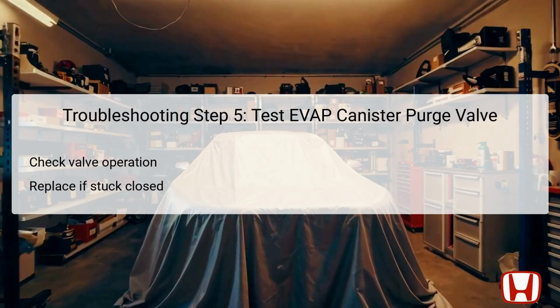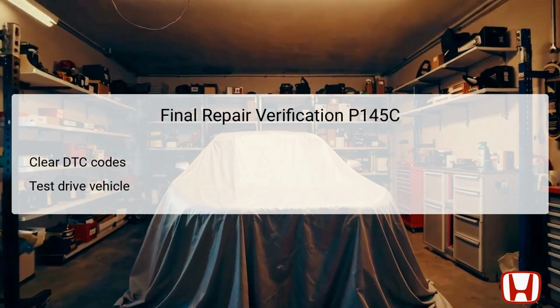emissions issues. After completing the necessary repairs prompted by the troubleshooting for DTC P145C, it is imperative to perform a final repair verification. Start by clearing any stored DTC codes from the vehicle's onboard diagnostic system to reset the monitoring processes. Once cleared, conduct a test drive to ensure that the vehicle operates smoothly and that the previously illuminated check engine light does not reappear.